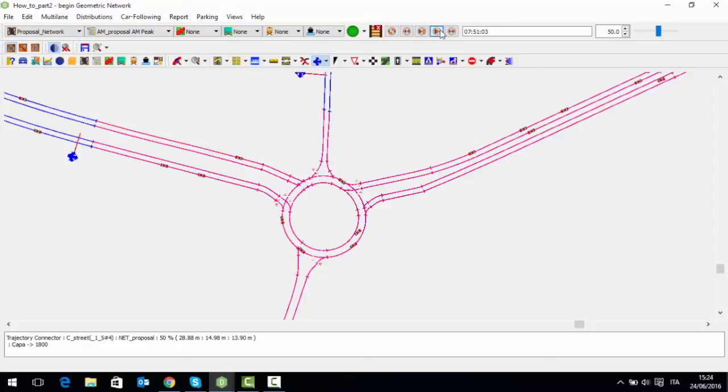In this way, we can easily compare the behavior of the two models, and we can assess the impact of any layout using data collectors to extract results such as delays, journey times, flows, and so on. The possibility to run in parallel two different scenarios allows us to save time, because using layers it is possible to move and to share objects among different scenarios, as we did. And it is possible to minimize errors when a change is required on elements that are shared over different scenarios.